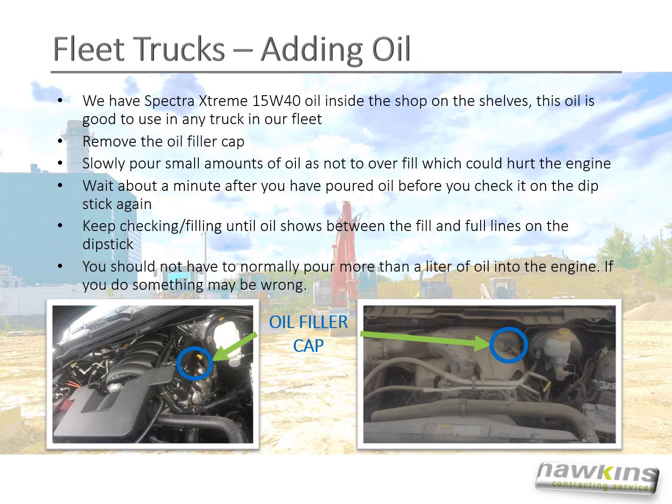Adding oil. We have Spectra Extreme 15W40 oil inside the shops on our shelves. This oil is good to use in any of the trucks in our fleet. Remove the oil filler cap. Slowly pour small amounts of oil so as not to overfill, which could hurt the engine.